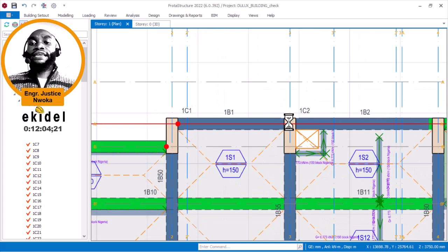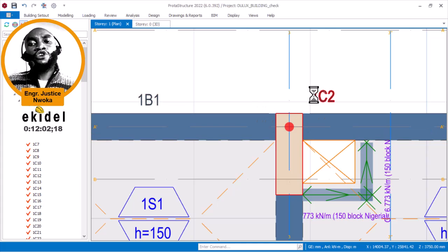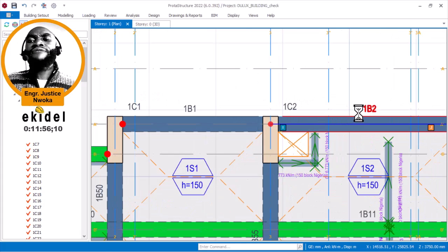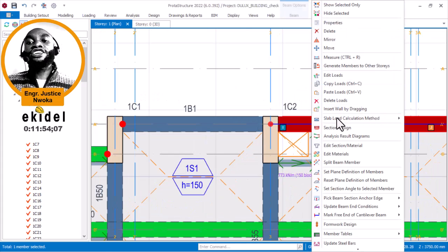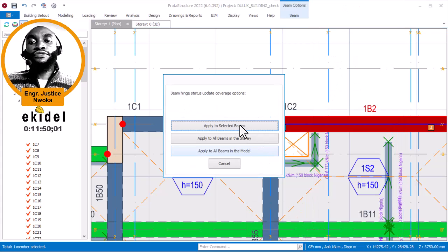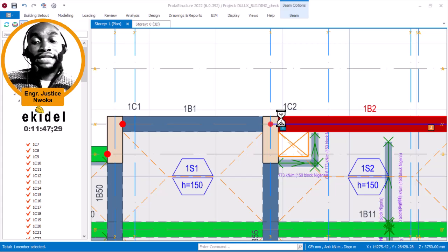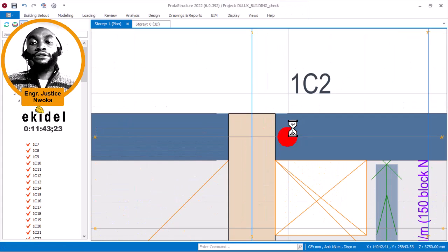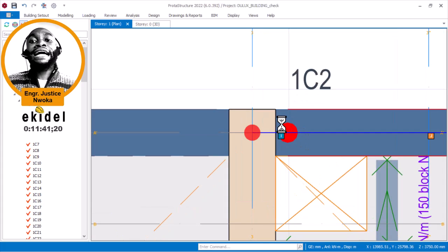Now in this case right now, you must not hinge a continuous beam at the mid span. So I'm not going to apply any hinge here. If I come now and apply a hinge at I on this, that means that I have done a blunder. Okay, I have gotten it wrong, because moment cannot be 0 here.